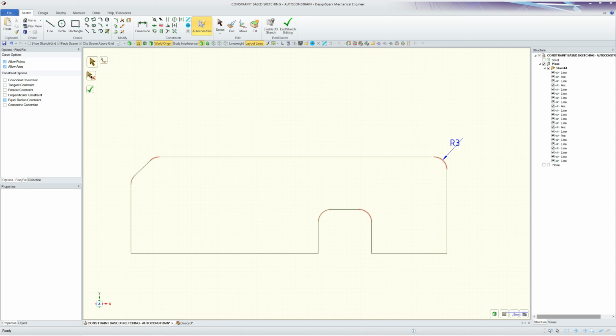I've got equal radius constraint already activated, and it was showing 4 problem areas. So if I now use this exclude problem area by just mouse hovering over any curve, it will show the constraint that it won't make. So let's not make these an equal radius constraint. And then I'll turn it to green. But by just mouse hovering, other possible constraint exclusions are highlighted. So accept.